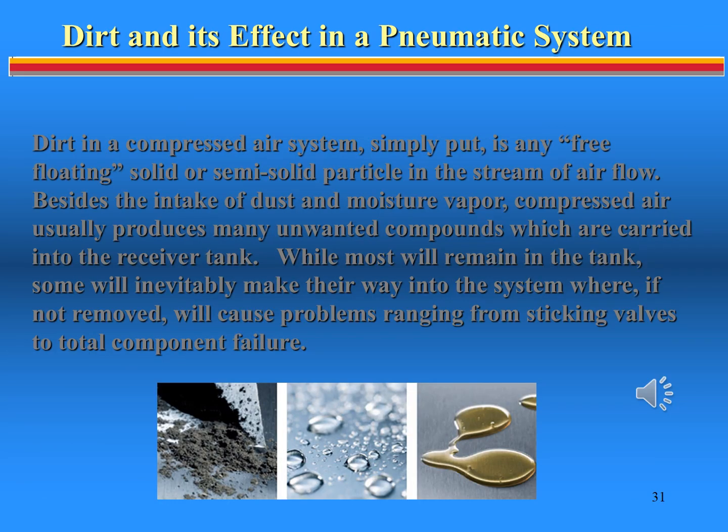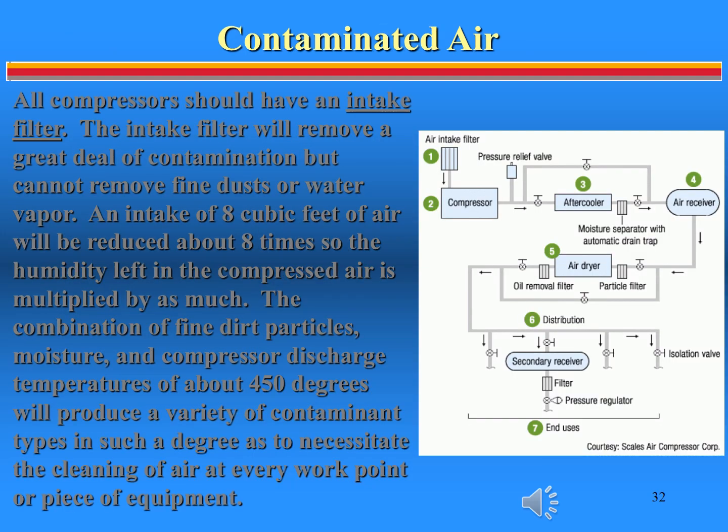This slide shows what is being taken in by the compressor and compressed. Compression of the air causes heat buildup, and this in turn results in chemical changes in the air. The presence and location of the intake filter is critical, as it is the primary line of defense for pneumatic systems. Great consideration should be given to the location so as not to place a filter in an environment that will decrease its service life. In addition, the length of the intake piping on some systems is very long and must be sized correctly to reduce pressure drops. Filters should be easy to access.